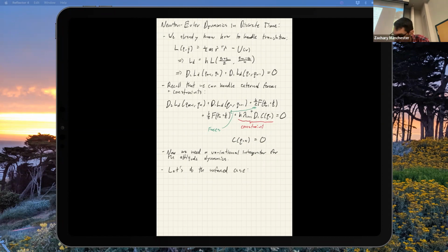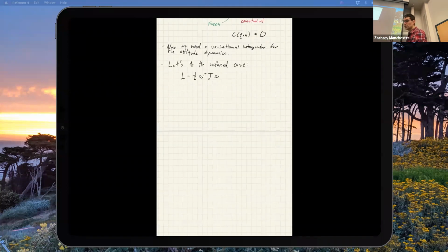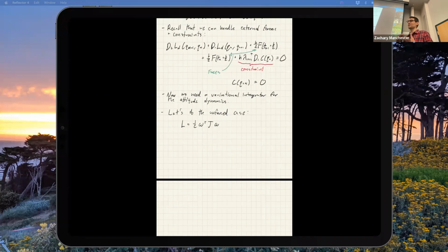Okay, so our Lagrangian, like we did before, is this guy, where you've got your inertia and your angular velocity. The only real trick here is that there's weird quaternion stuff that's going to happen. We talked about how if I just naively plug this in, you don't get the cross term, the Coriolis term. So you have to be smart about the quaternion stuff. Basically, there are two key tricks here. One is not a surprise: you have to do the quaternion attitude Jacobian derivative stuff when you take the derivatives, which we'll see, not a big deal. The other one is how you get this omega.